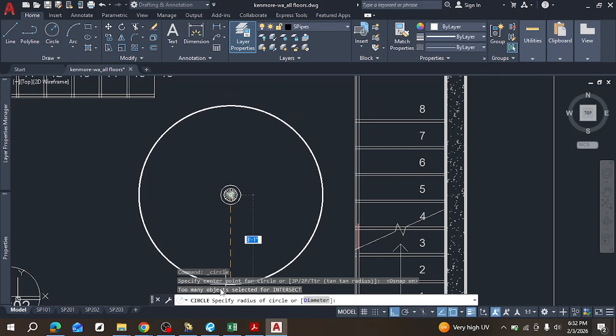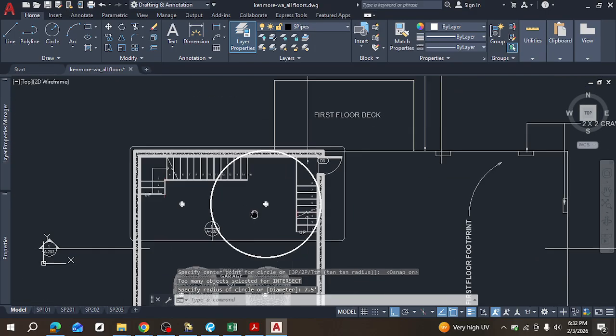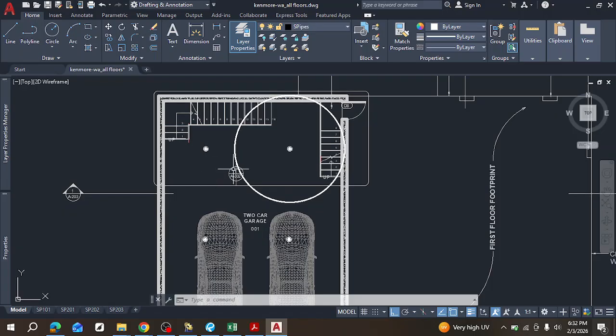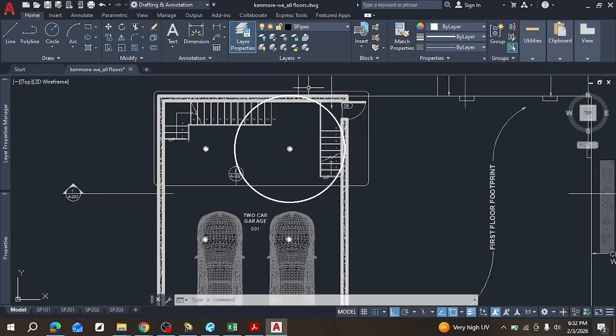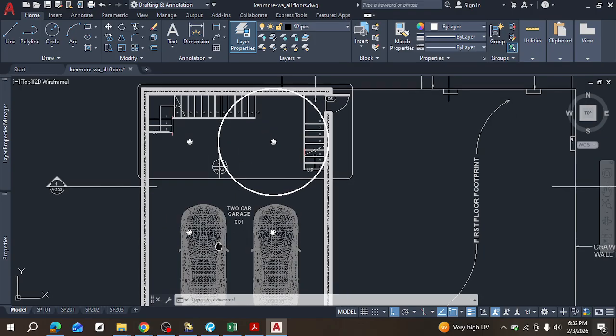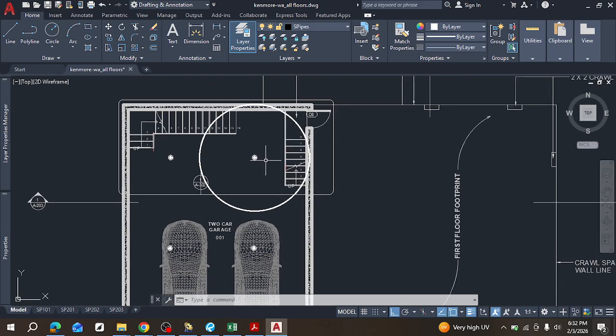So radius will be 7.5. I'm going to type it, 7.5 feet. Okay, that is inches, feet. Enter. Alright, so this is the coverage of each of the sprinklers. And you see that I've already arranged it in such a way that this one covers here, and by the time we cover here, I mean, I already did this because I didn't want to spend too much time arranging it while on this class. So you can see from the arrangement.